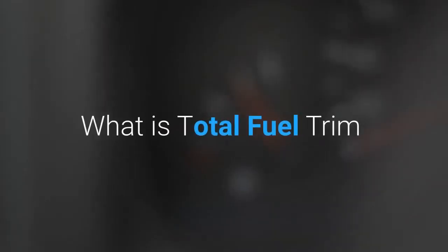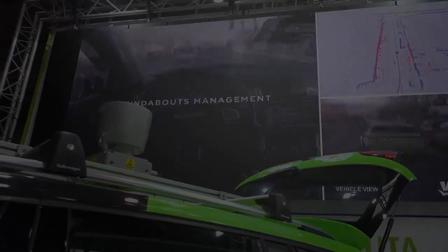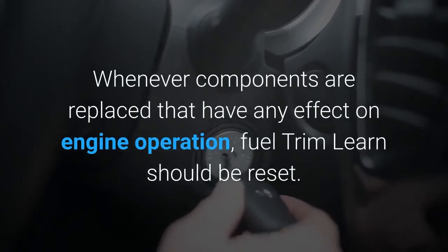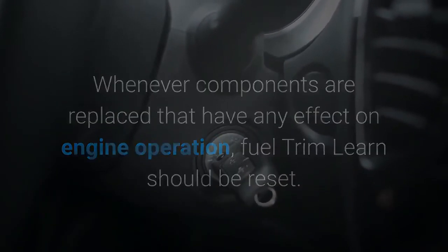What is total fuel trim? Short-term fuel trim plus long-term fuel trim should be plus or minus 10% for the best fuel control. Whenever components are replaced that have any effect on engine operation, fuel trim learn should be reset.